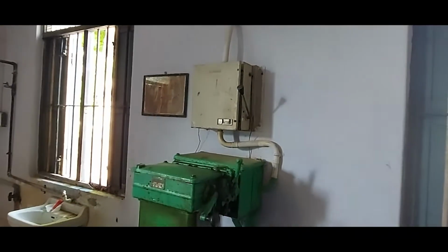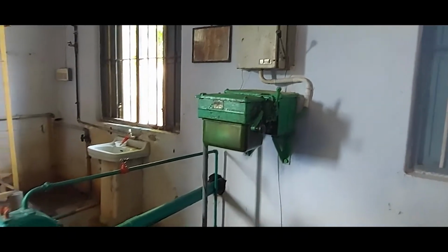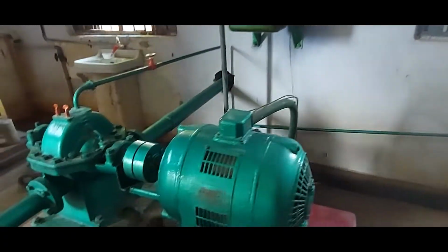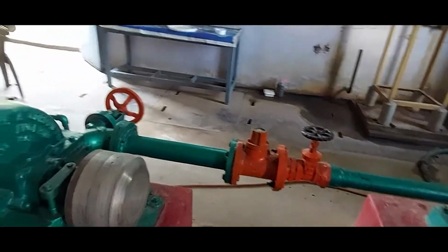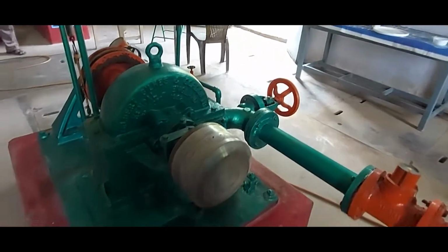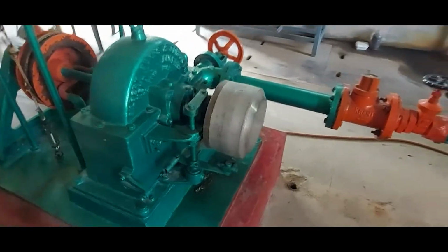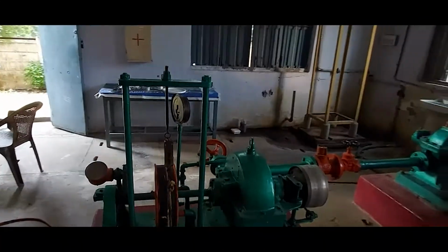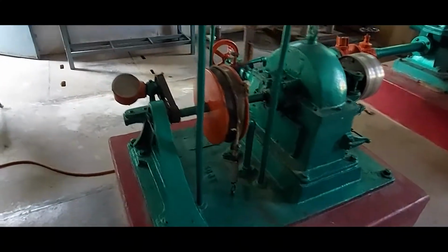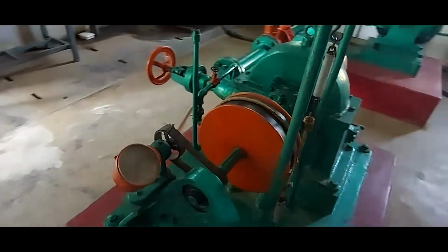Now move on to turbine. A turbine is a machine which uses the kinetic energy of fluid and transforms it into mechanical energy through a designed mechanism. Pelton turbine is an impulse turbine. The objective of this experiment is to test the Pelton turbine at different loads and spear valve settings and produce curves that show the turbine performance and the effect of different spear valve settings.